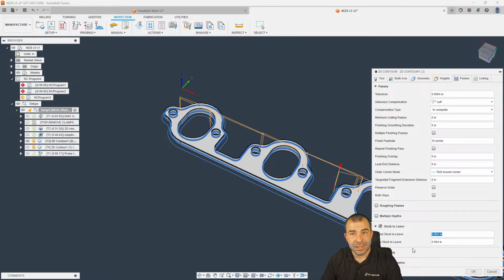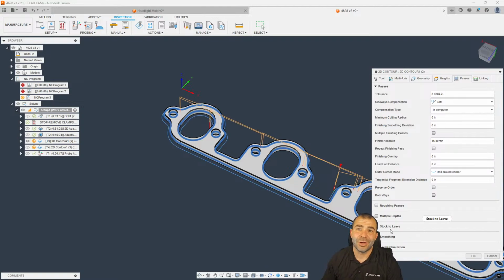And again, based on millimeters, guys, if I was to go in and say 0.5 millimeters, it would cause smoothing to happen, or 0.05 millimeters would cause it, less than, technically, is the way it's calculated. When you don't have stock to leave, it always goes to the tightest. But if he wanted to, he can now control it with tolerance here. But I don't recommend either one of these, right?